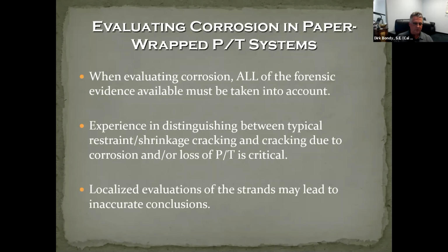And I keep saying that just trying to evaluate locally the strand itself may not give you a good conclusion. You could be looking at a section where the strand looks terrific, and 50 feet away, it's corroded and broken.